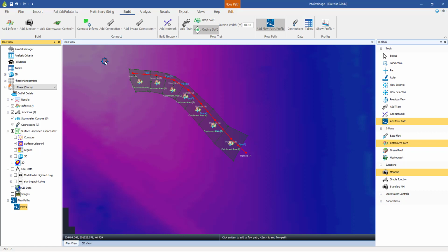Here each storm has a sort of start, a middle and an end, and we have to run that through dynamically to see the pipes. The pipes are allowed to fill up, the manholes are allowed to fill up as well and then drain down, so long as at no point is there flooding on the catchment surface.